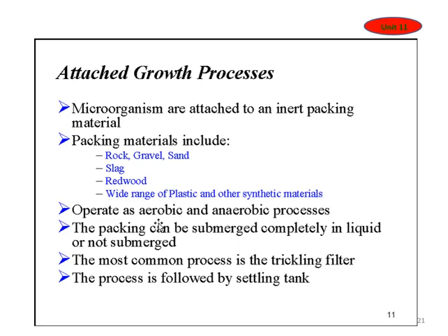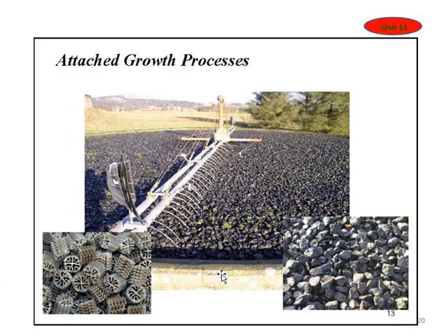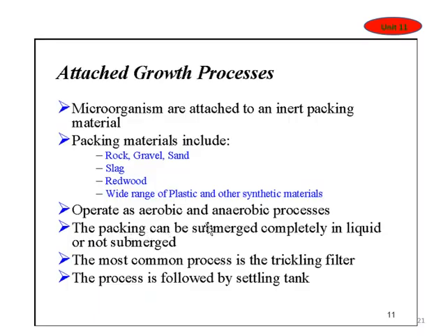Air is not needed everywhere; in some places, when the wastewater goes inside, there may be less oxygen, so it will be anaerobic also. The packing material can be completely submerged, filled up to the top with wastewater, or it can just be sprayed. The most common process is the trickling filter.